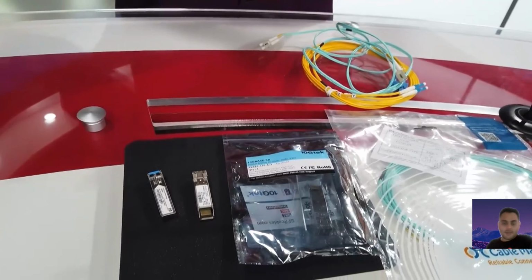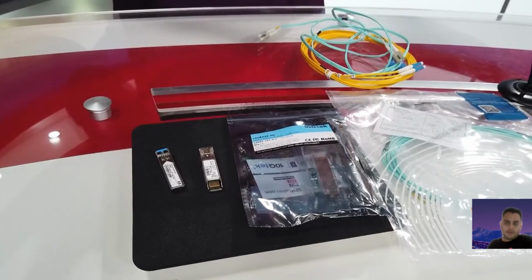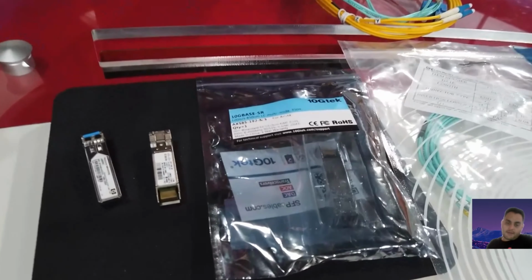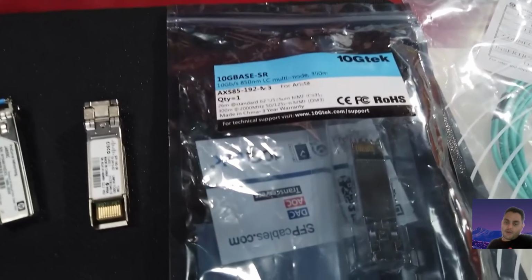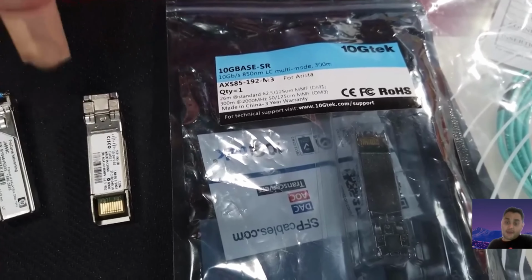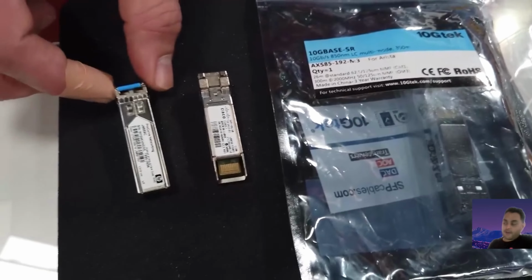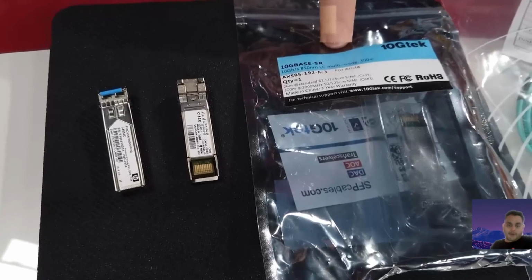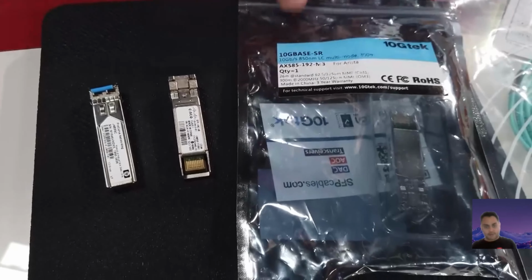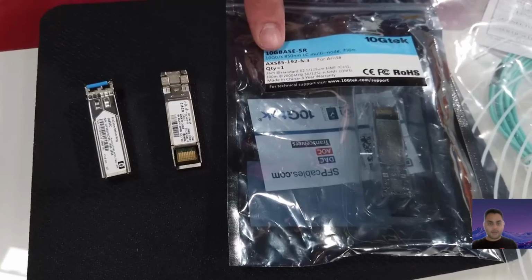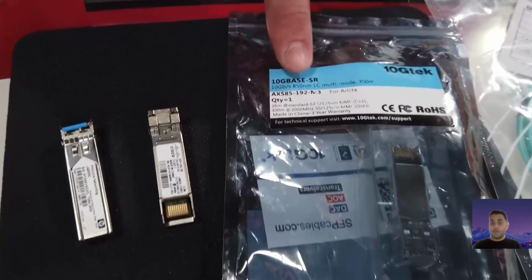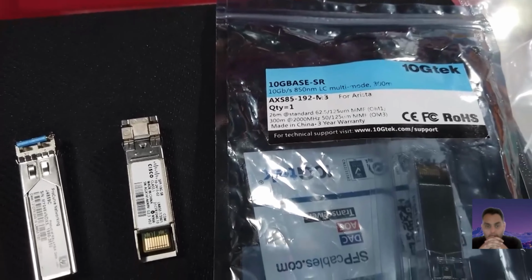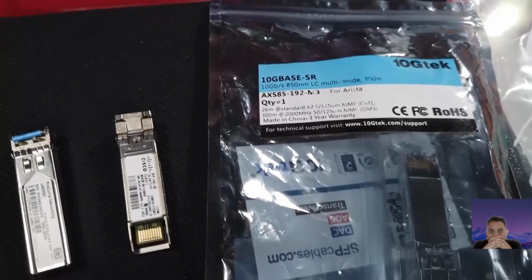This is a multi-mode cable that has a distance of 300 meters, and you can actually see this right here on the package, that it's also 850 nanometer wavelength. And they also have them labeled here on top of your little modules. A little hard to see, but the great thing is we can see the labeling in the package too, and it does tell us the standard. It tells us that it's 10G network, it's 850 nanometers, that it is multi-mode, and then it goes 300 meters length. So remember, multi-mode fiber has a shorter length than the single mode fiber.